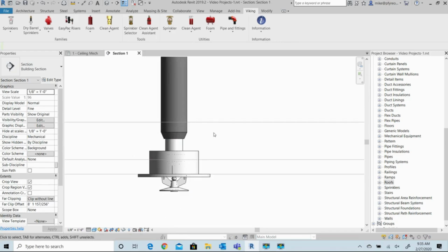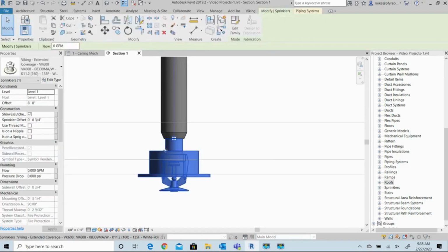If you're using the standard supplied Revit MEP template pipe and fittings, we provide another adjustment option. The pipe connector for the sprinkler is at the end of the sprinkler thread, and the connector for the supplied fitting from Revit is the face of the reducing fitting. We provided another option to adjust for the makeup of the sprinkler into the fitting. Notice that the pipe is adjusted, not the sprinkler. It's a simple checkbox to select that option.